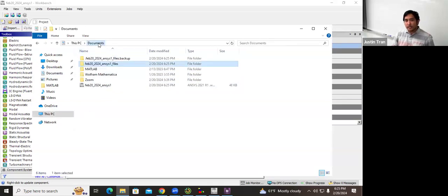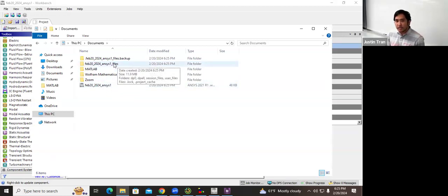It gets a bit complicated. You would think you could just transport both of these files to your home computer, but it actually causes errors, because what ANSYS expects is that when you launch this file, it links directly to the locations of these files. If you move this between computers, even if you move these files to a different folder, it's going to cause errors when you try to launch it again.